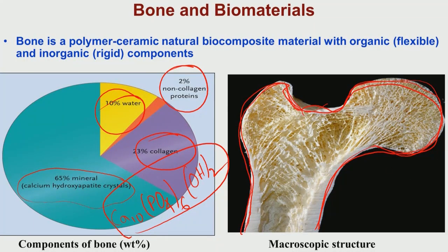So, one thing that one can address this with is near net shape processing. That means you consider the design file of a bone to be replaced, and then you export the design file to the additive manufacturing machine, and this machine will decompose the design file into capital N number of alternating layers, and there you can just use this layer by layer fabrication technique.